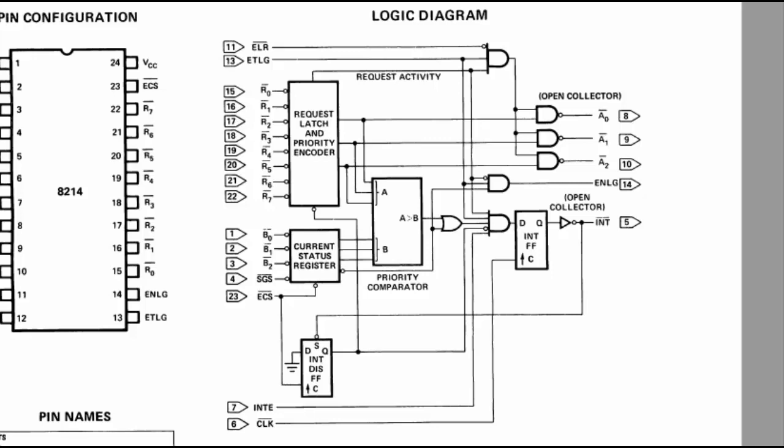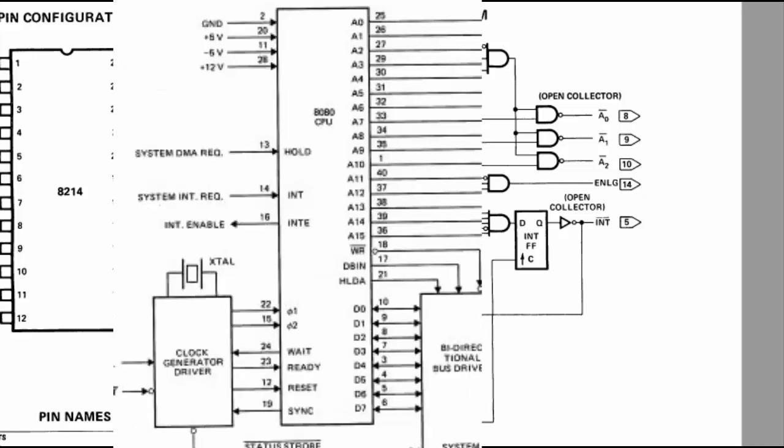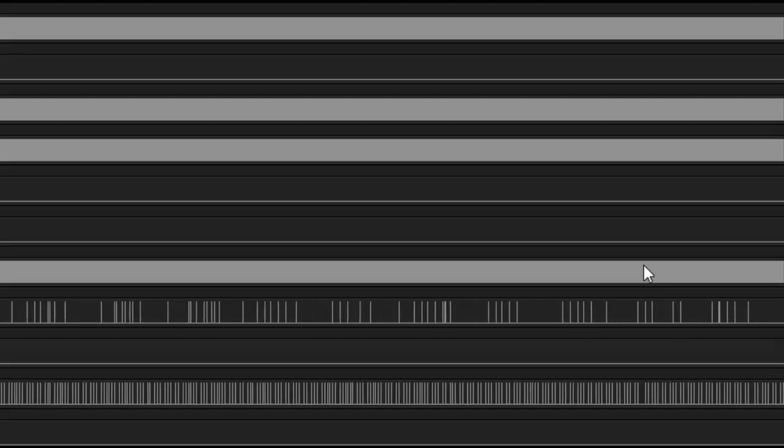But the fact of the matter is, of the 40 pins on the 8080, this is the only one we have direct control over. We can issue an EI and a DI, and we can toggle this pin. So one of the things that I do in my confidence test is, as soon as I boot up, I toggle that pin to see what is going on. So let's look at the waveforms in the confidence test.